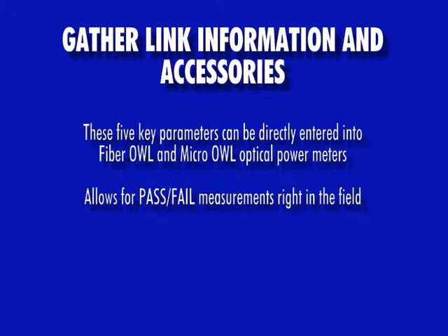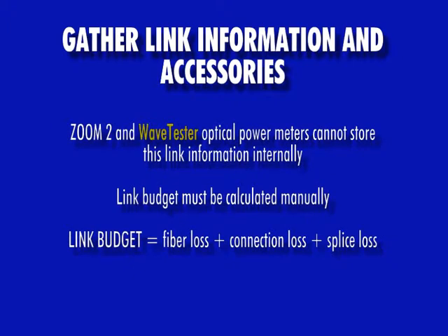When using a micro-OWL or fiber-OWL optical power meter, these parameters can be entered directly into the device to calculate the link budget. However, if the link budget needs to be calculated manually, this is done simply by adding together the fiber loss, connection loss, and splice loss.